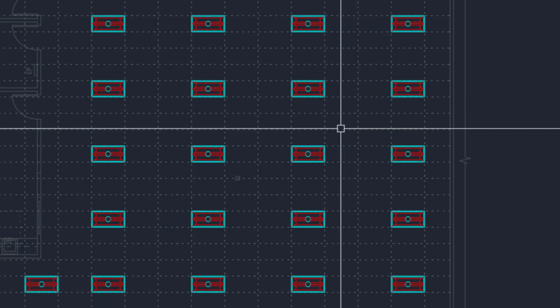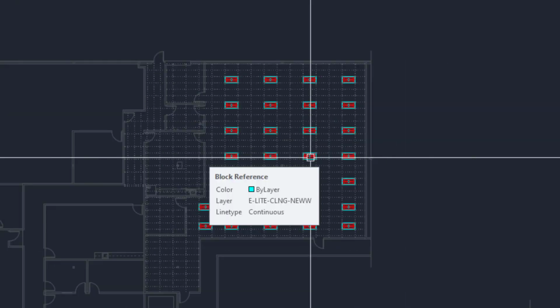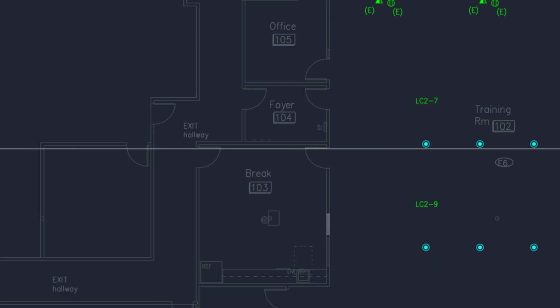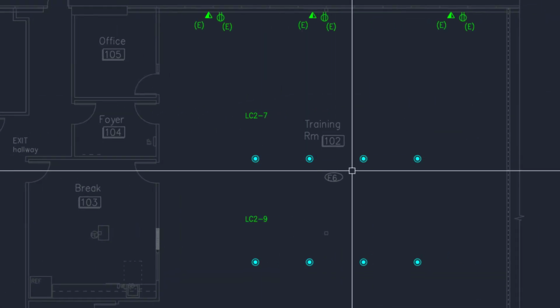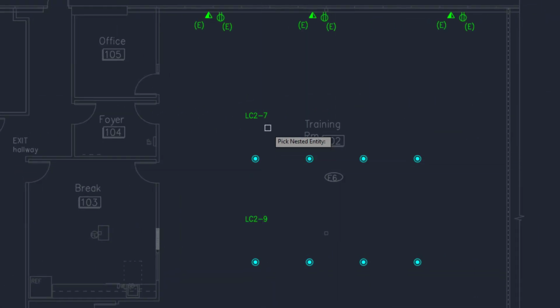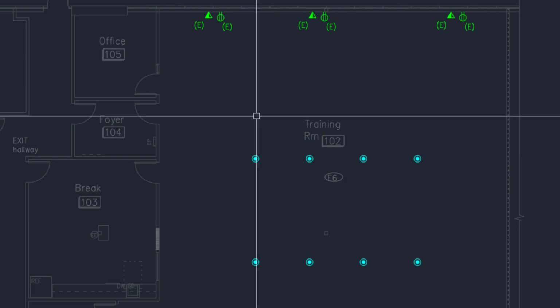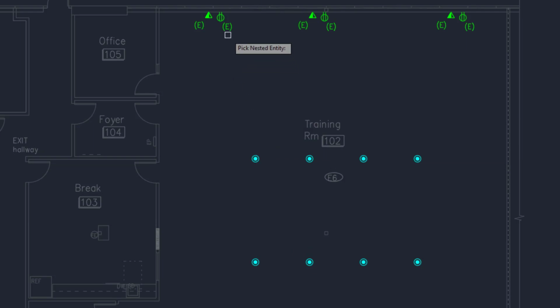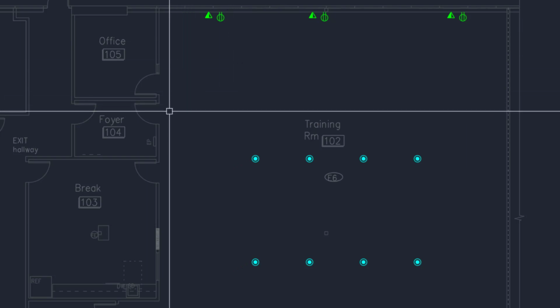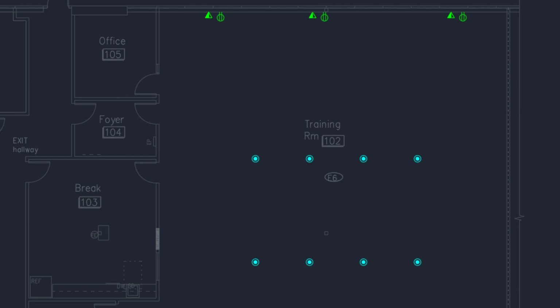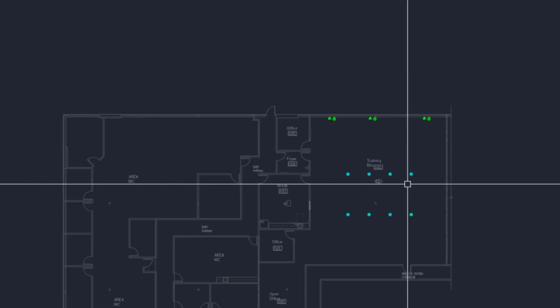Now I've picked that and freeze the lighting conduit and have a lighting plan. The power distribution conduit's already been frozen over here. I press enter to enter the command again, and I freeze the new tags and the existing tags, and I have a plug layout. So just the quick little changes up here, and the ribbon was tracking layers for you.